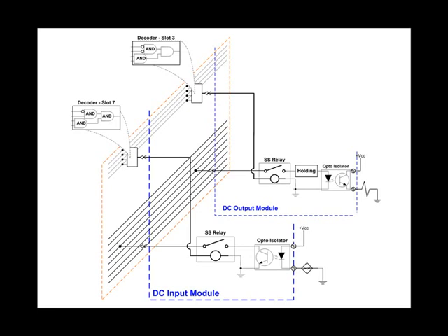And when it comes time to send out the output states, which are stored in memory as a result of the logic, to that slot, it will be one word at a time until all 32 words are transferred from the processor's memory into the memory in the DeviceNet scanner card's memory. This sequence is repeated to transfer the 32 words from the controller's memory to the 32 words in the DeviceNet scanner card for the outputs.